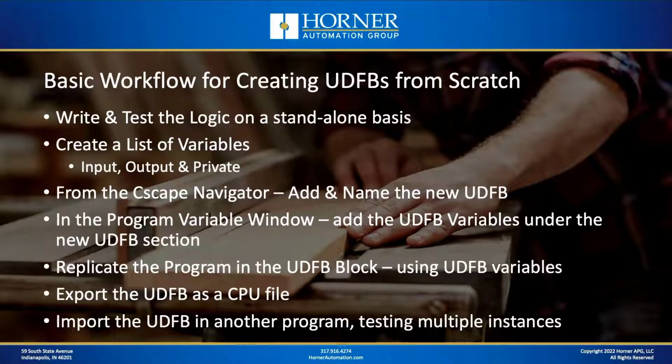It has a file extension of CPU. And then following that, you're going to go ahead and, using another Cscape program, you're going to import that UDFB so that you can test it, preferably with multiple instances of that same function block. So that's the basic approach you're going to take for any UDFB. Now, yes, there's lots of steps, but again, we need to stress the benefits are many.